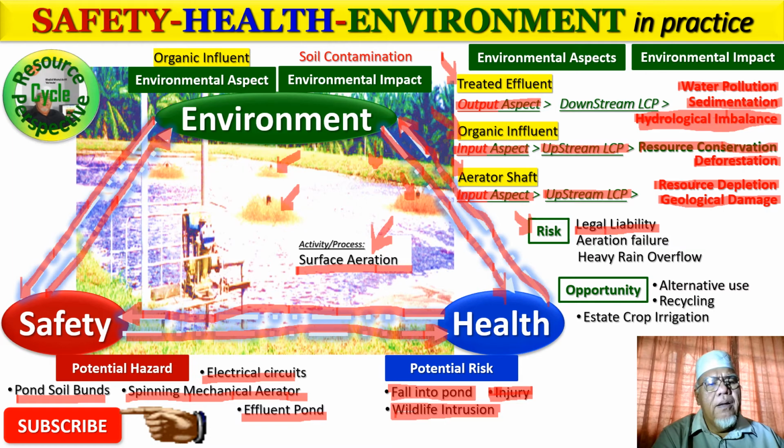Failure to do that would bring in legal liability. On top of that, there is the discharge standard that we have got to comply with. We have got to ensure that this particular surface aeration would be able to really bring down the BOD level to stipulated limits prior to discharge, prior to releasing it out of the system.